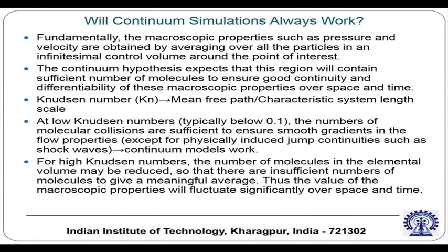Typically for Knudsen numbers below 0.1 you can use the continuum modeling safely, maybe adjusting the boundary condition with a slip based paradigm instead of a no slip based paradigm, but still you can use the continuum considerations with adjustment of boundary conditions.